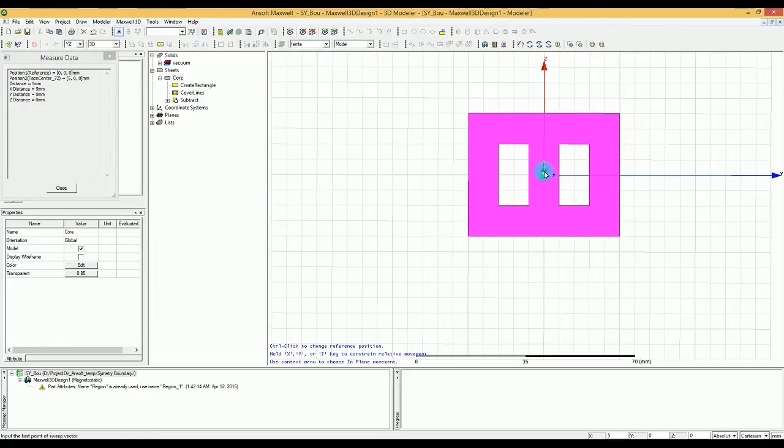And over here you just put the center, so 0, 0 and 0 for the xyz, and the amount of sweep is going to be -10 on the dx part, so -10 and nothing else for the others. So that should be okay.